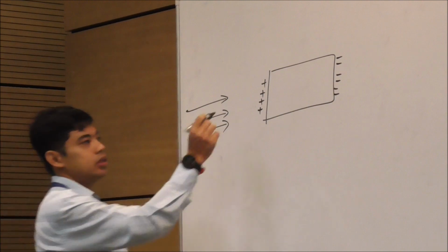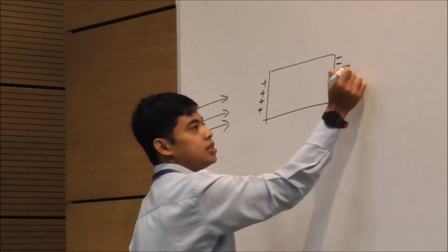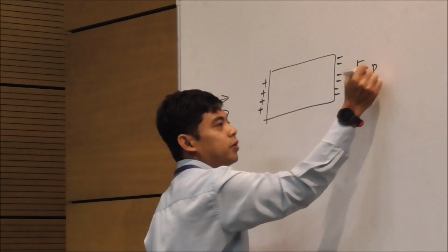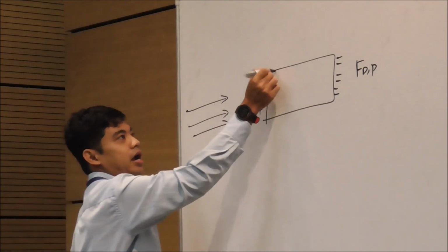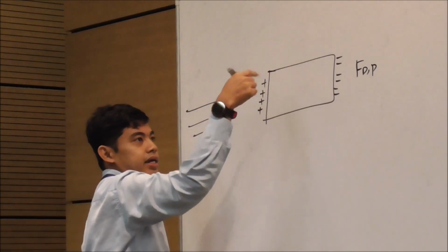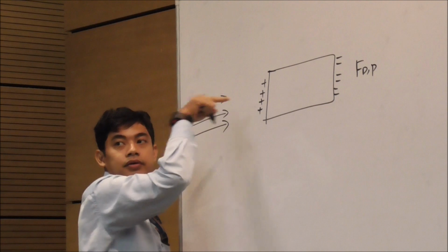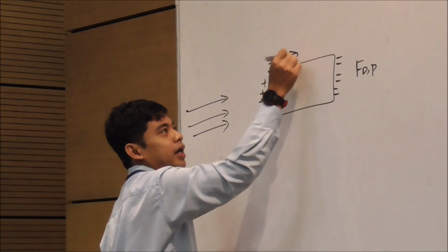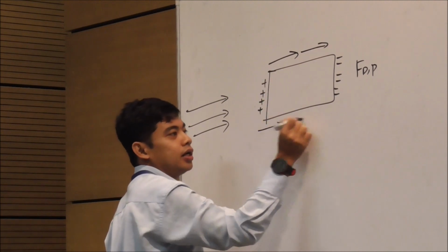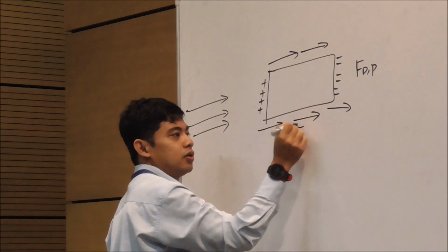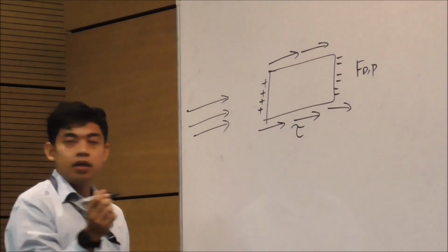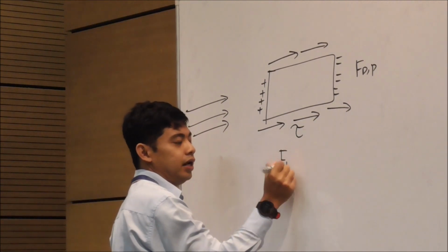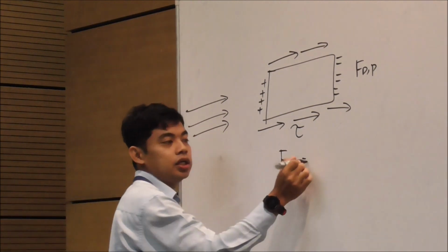On top of that, if you look at this, it is F drag due to pressure, but since you have this also, right? In this case, the area is the frontal area, right? Whereas if you are looking at the top of the plate, here and over here, there is also a shear, right? This shear will provide FD due to friction.